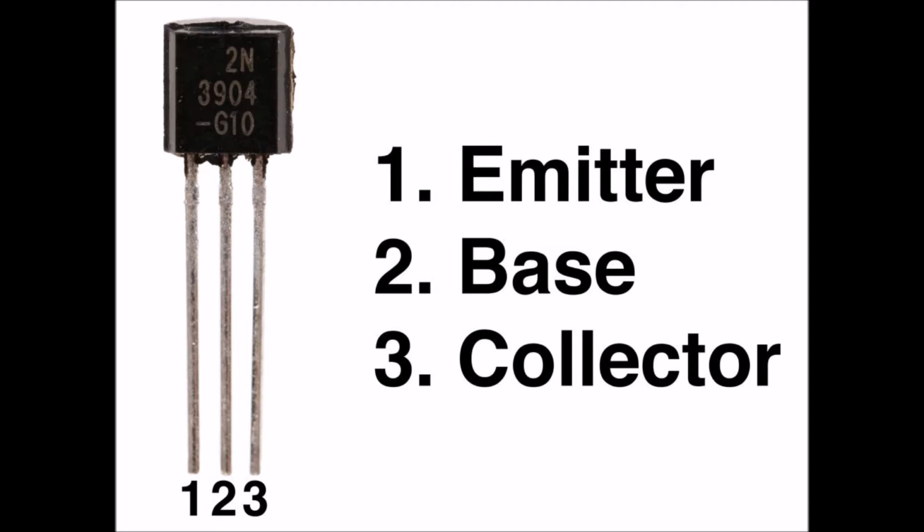Common emitter configuration. A bipolar transistor can be wired up in three general ways. We can ground the emitter for the signal, we can ground the base for the signal, and we can ground the collector for the signal. An often used arrangement is the common emitter circuit. Common means grounded for the signal. Figure 22.9 shows the basic configuration.